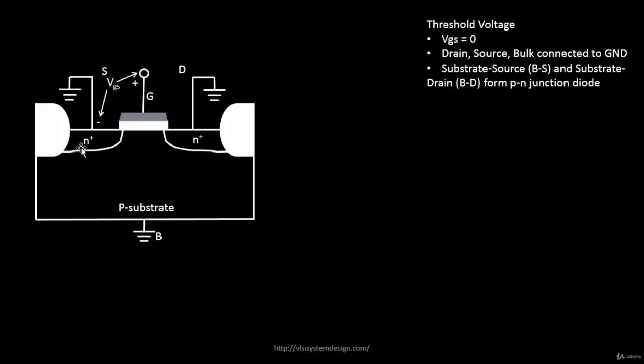Now when we do this, you see this is a p-type substrate, and this is an n plus area, and this actually reminds us of the famous p-n junction diode. Whatever behavior we talk about over here represents the p-n junction diode characteristics. Whatever happens in a p-n junction diode on the application of potentials at either terminal of the diode, exactly the same behavior will be replicated over here, only there are two back-to-back p-n junction diodes connected over here. That's a basic p-n junction diode.